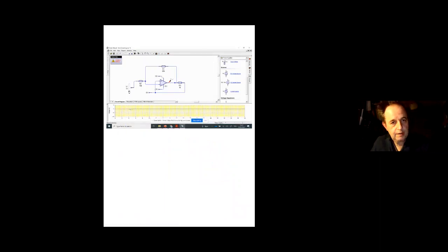Biggest thing in this one is that if your input voltage is positive, notice this is negative. Okay, so when you're doing graphs, make sure you're going negative if you've got a positive, and if you've got a negative, you'll be going positive, if they are inverted. So in this case, we've hit saturation at that point again. Input voltage is positive, but my output voltage is negative. Okay, and same thing if it comes to an AC.